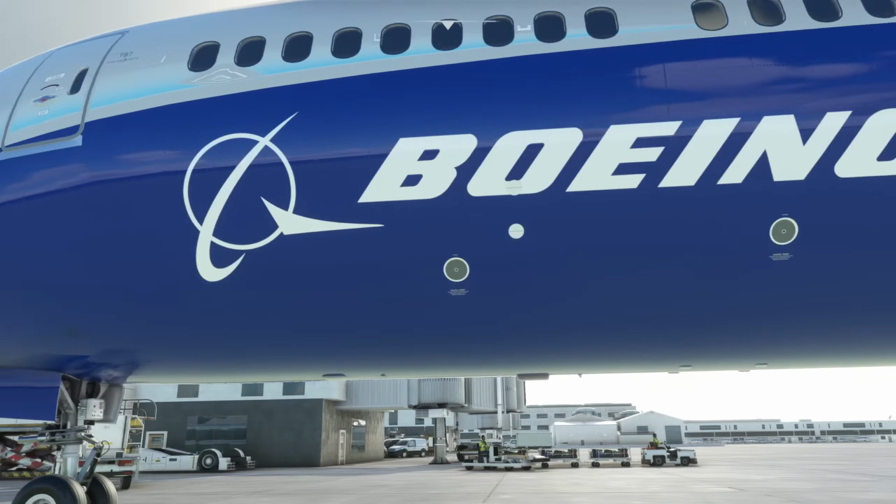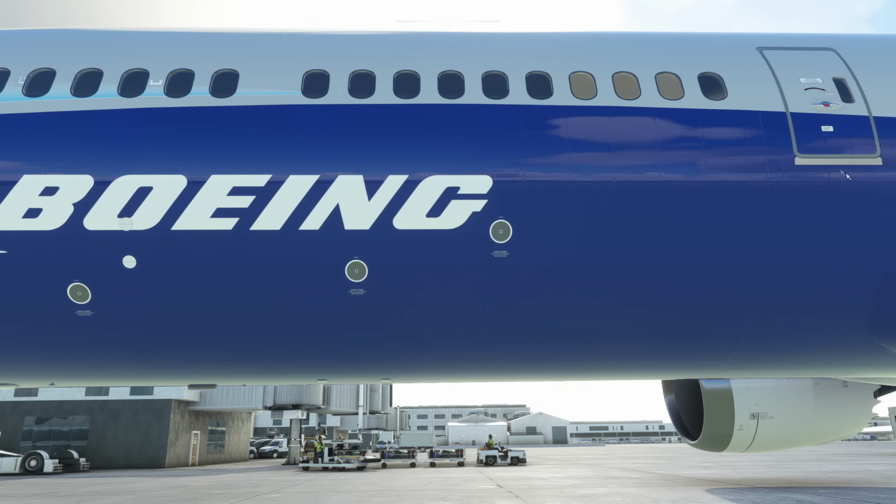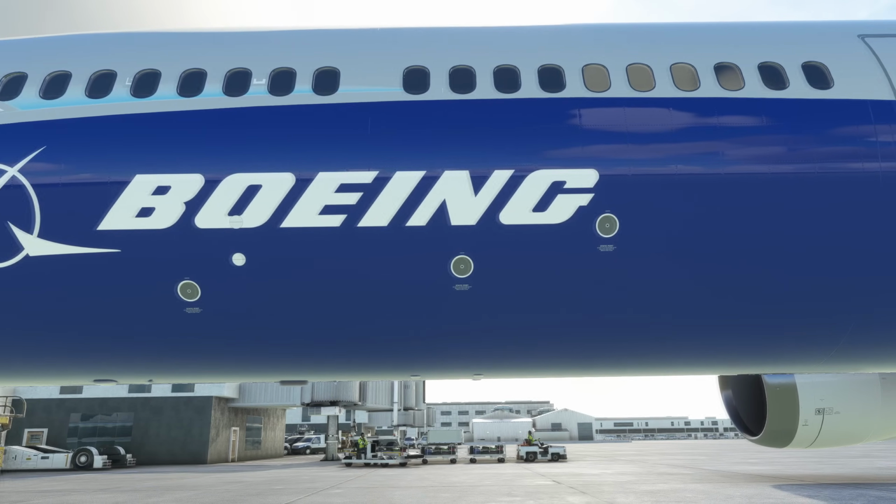Now there are further back, they're not modeled on this version, but there are negative pressure valves. So they are there in case the fuselage does not repressurize and you descend, and then you have positive pressure outside, now squeezing the airframe in the wrong way. So they would then open and allow the air into the cabin to relieve the pressure in that way.